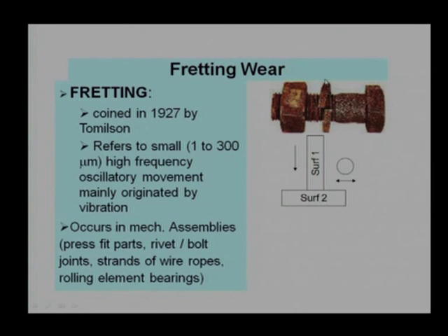Just to demonstrate what we are saying, let us take one surface and another surface. They have a contact under load, that means the contact is under stress. In addition, they are getting some sort of oscillatory motion, some sort of periodic motion, which is continuous, and we are talking about this motion in terms of microns, which will not be detectable, right. That is going to cause a problem.